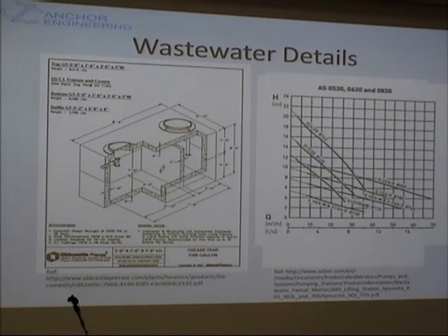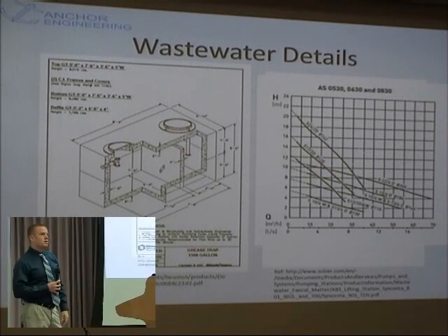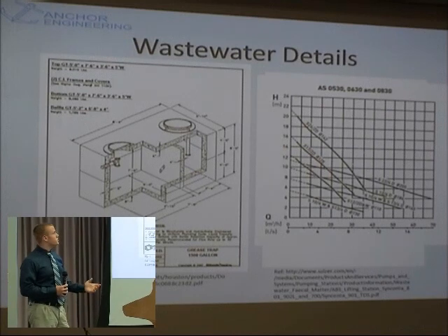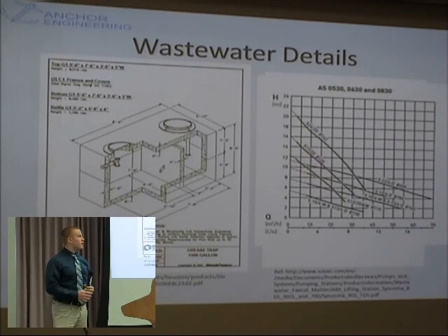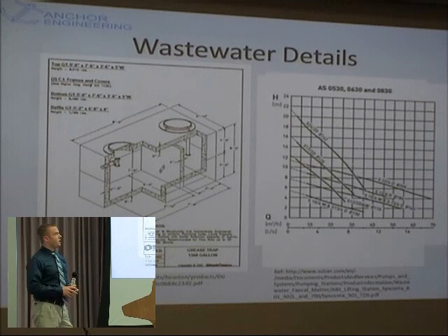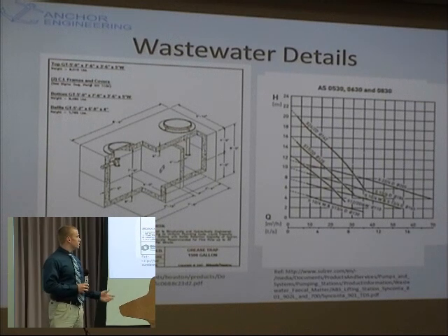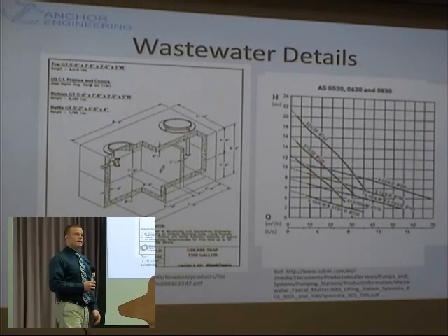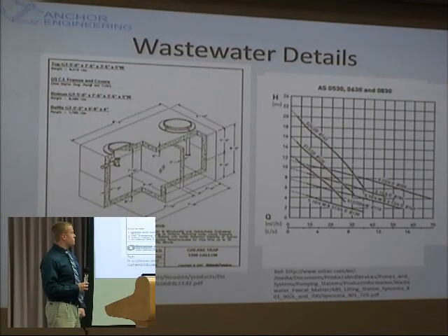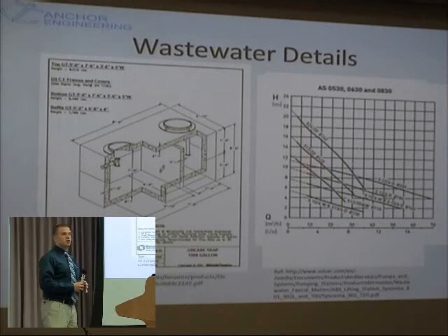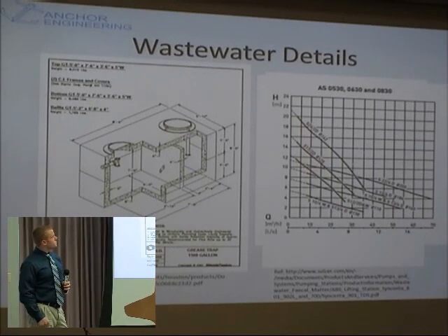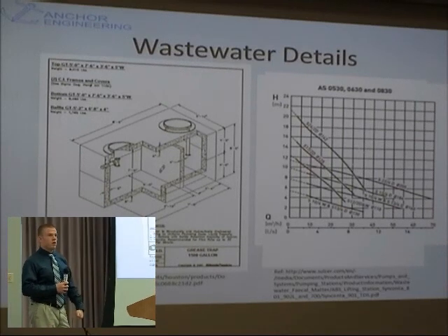For the grease trap, as I mentioned, coming out of the restaurant, the Department of Environmental Management requires grease traps to be able to have capacity for 50% of the daily flow from a restaurant. Our restaurant was estimated at 5,200 gallons per day. So dividing that in half, we needed 2,600 gallons per day of capacity. To achieve this, I selected two 1,500 gallon grease traps, which would look something like this, in series. And that pretty much solved all the wastewater problems for our site.